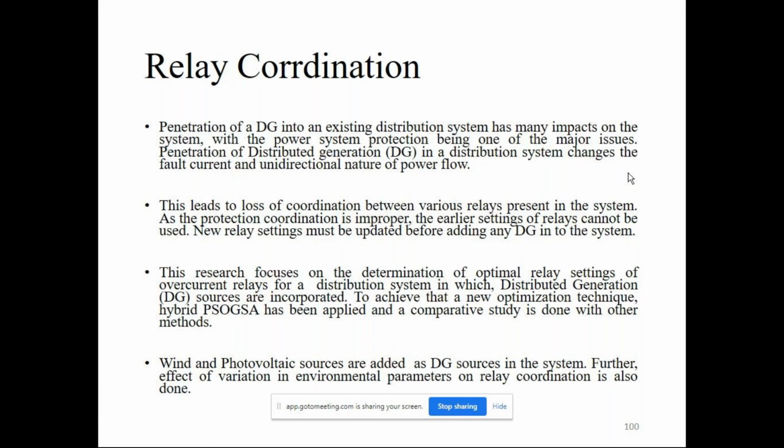Now you see, you have the bidirectional power flow with respect to the renewable penetration. So there are a lot of issues: sympathetic tripping, blinding of protections, the zone boundary. These are a lot of implications with respect to the renewable penetration, and the converter-based dominance in the network does not give a straightforward sequence component.